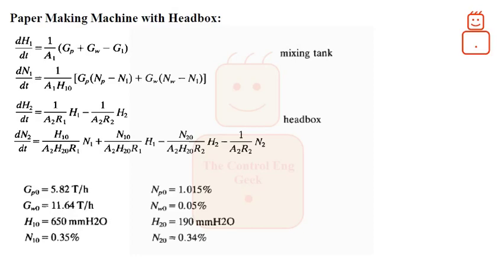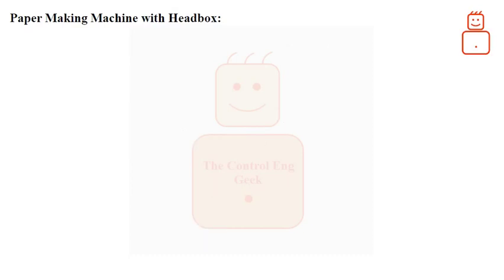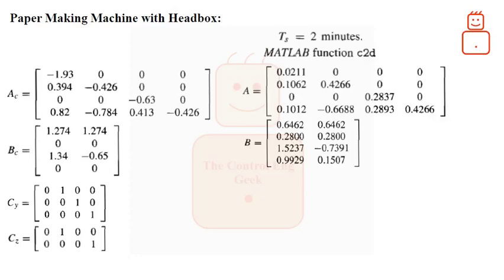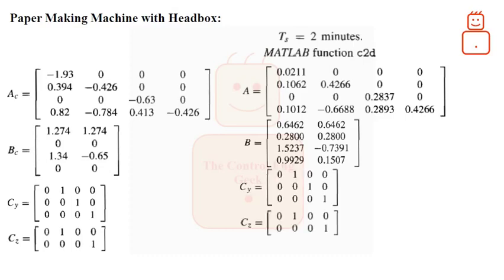One can use the following defined steady-state values. Thus, using linearization technique, we can have the following linear, continuous set of first-order ordinary differential equations in this form of the state space. Here the time is given in minutes rather than seconds. Assuming a sampling time of 2 minutes, one can utilize the MATLAB function c2d to discretize the derived linear state space. The corresponding result is given as. Here, both measured and controlled output relations remain the same as with the continuous time state space.